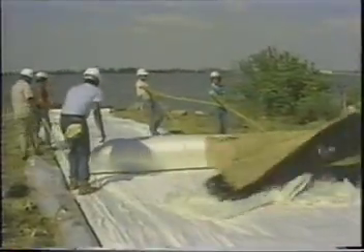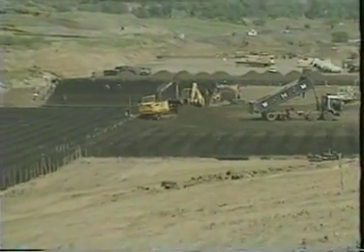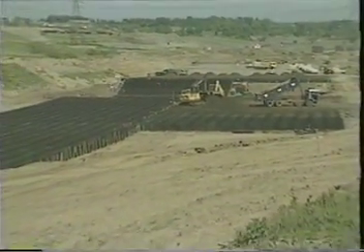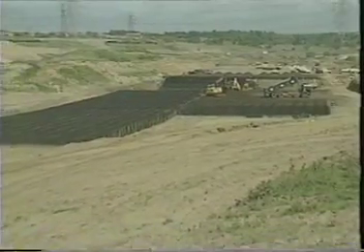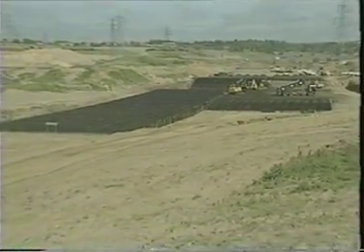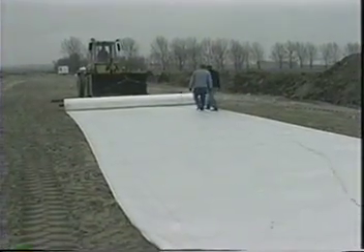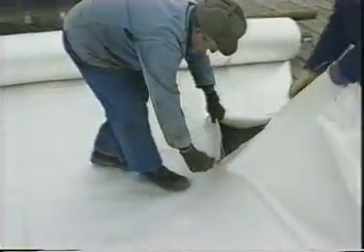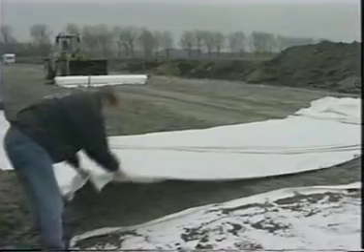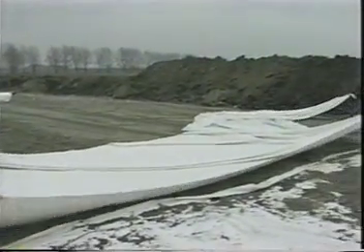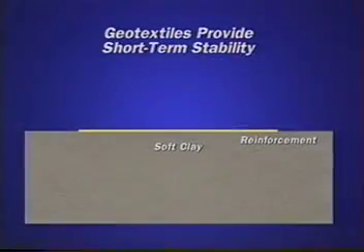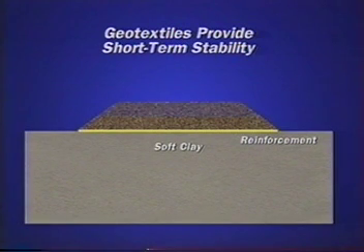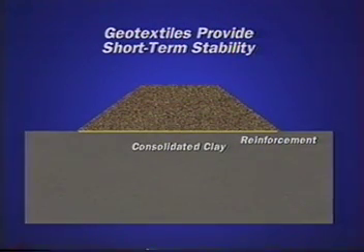Strong geotextiles and basal mattresses may be used to reinforce the base of embankments constructed over weak foundation soil, but in two different ways. A layer or layers of a high-strength geotextile can be placed across the base of an embankment constructed rapidly over a deep deposit of soft clay. The fabric provides stability to the embankment during the short term and becomes redundant once the clay foundation soil has consolidated and gained strength.